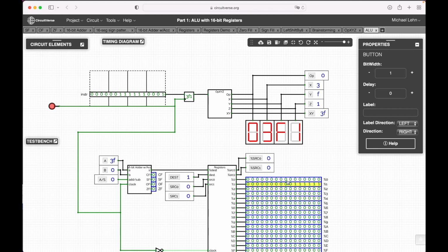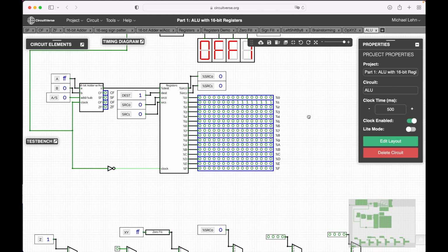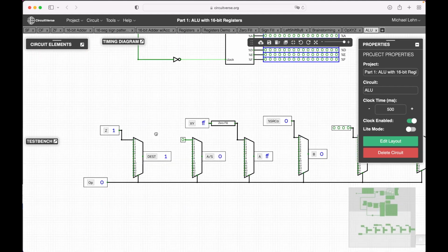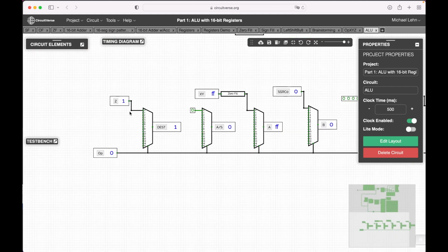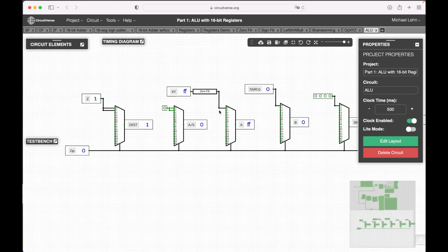Here I filled now the bit pattern of 1. Actually, I wanted to fill it with this bit pattern. So if I would now do this operation, I should get here this here left shifted, then 4 zeros and then 4 ones. So this will be my test case. Now for the implementation, there are only a few things to do. Here I just also connect this here with set. I also connect this here with 0, so this is the same as before. I also use here the 0 extension of x, y.